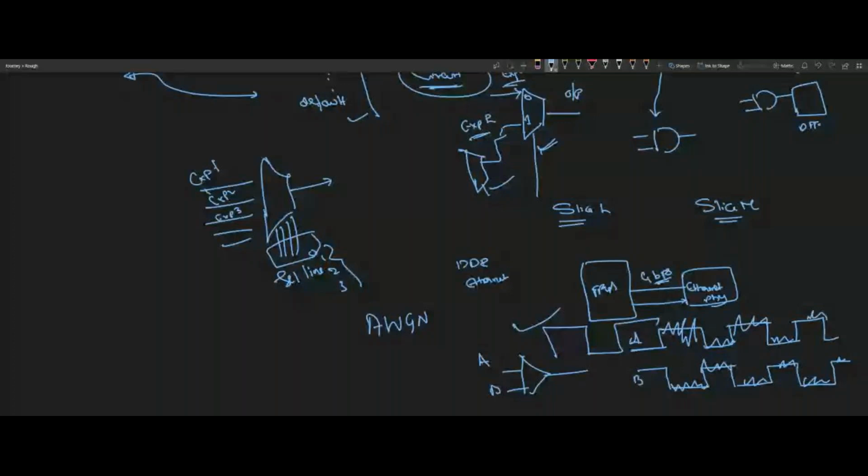One advantage in the FPGA is that you are not bothering about backend design, physical design, placement, routing, or rigorous STA. No, right? So here we have the advantage of saving all this money. Or else, assume you want to design one radar as an ASIC, you have to go for a lot of physical design and STA. It's a huge cost, right? So whenever you want permanent circuitry, high volume, mass volume production, then we go for ASIC.